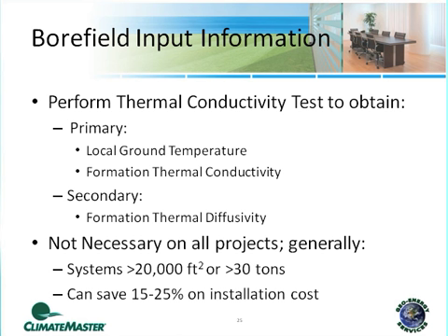But the reason you want to do this test is because getting these pieces of information will further reduce the conservativeness of what engineers typically do, and it results in a 15 to 25% lower installation cost because we've got more, better refined data. For me as the designer, if I were to do a project and I don't have TC test data information, I'm going to be conservative. I'm going to guess a lower thermal conductivity, a lower or higher ground temperature, something that gives me a bigger ground heat exchanger because I want this thing to work. I don't want it to fail. But if I have this TC test data information, then I'm going to be more refined and better off.